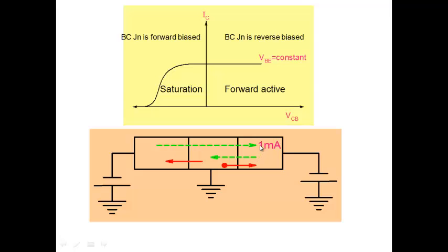And this is the situation here. Collector current becomes 0 here. And now if you want, you could even increase the forward bias even more, and you could make these currents stronger as compared to 1 milliampere here, and the current would reverse. Okay, so this is the situation in saturation region here. Both the junctions are forward biased, currents are injected here, currents are injected here, and as a consequence, the collector current is small here.